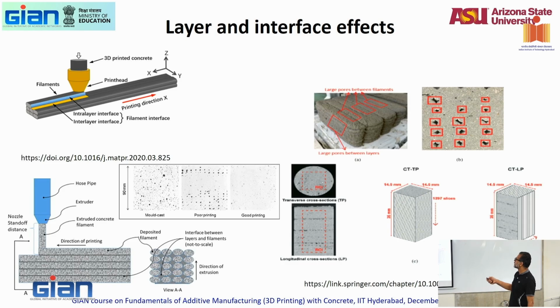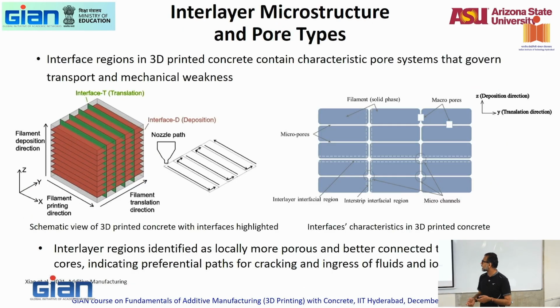So all of these very interesting ideas mean that if I want a higher strength, you saw the bridge yesterday and you saw how it was printed, right? You printed it and then flipped it, which means before you print, you should know how the bridge is actually going to be in the field, so that you can print in the direction along which you want the highest strength. That planning has to go in. You can't print any random shape. The printing path and the print direction also have to be accounted for.